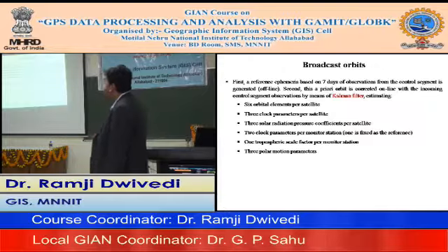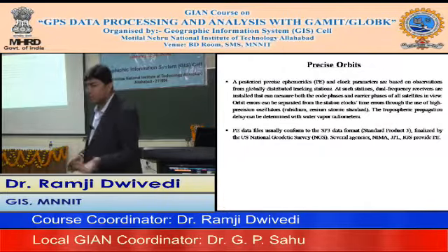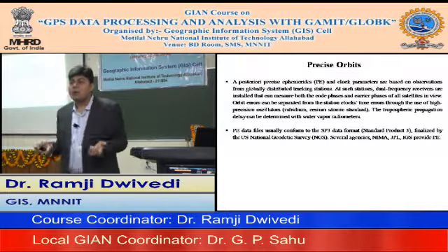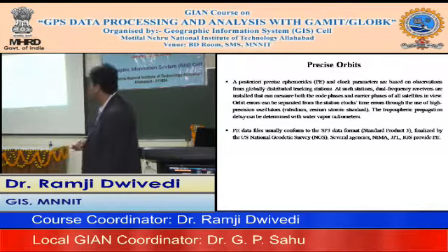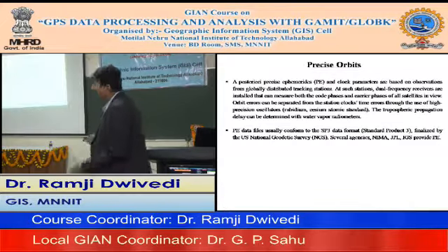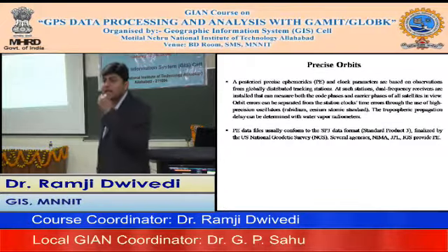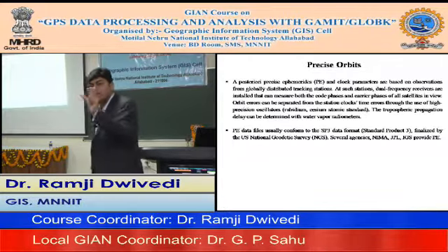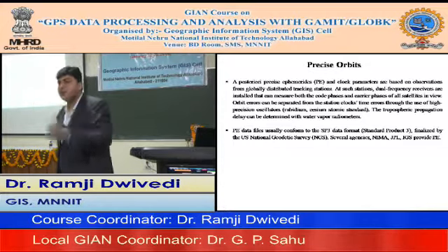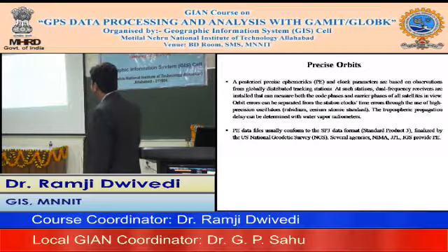And obviously the precise orbits are nowadays available within a few minutes, and you can download and use them to estimate the satellite position in XYZ directly. So if you go in the lab, you will make a folder of IGS, which is nothing but the orbital file downloaded from the FTP.